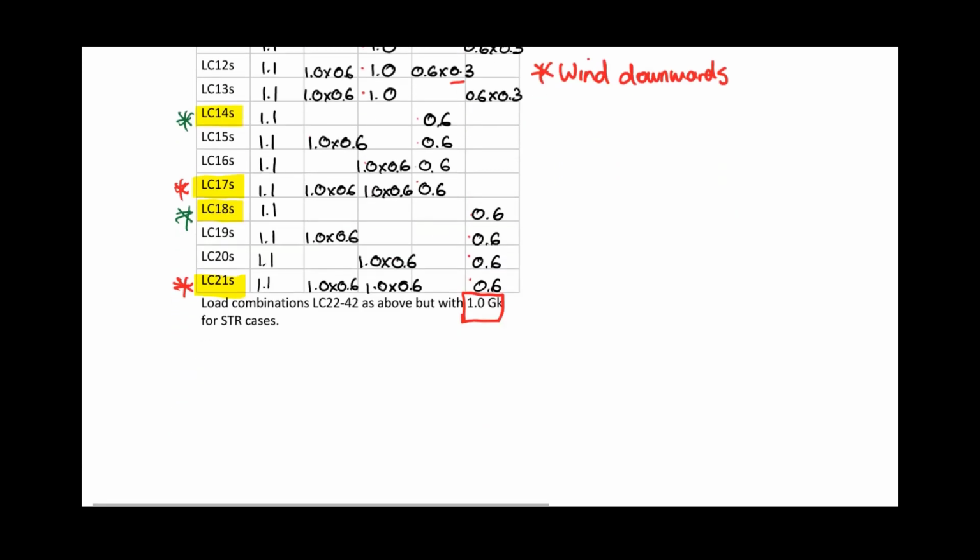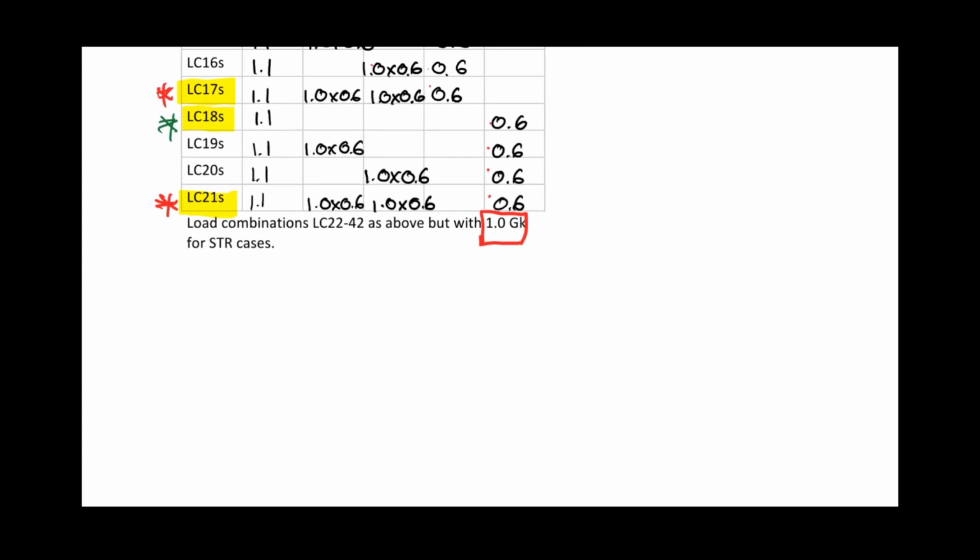And then just a final comment, finishing this one off, remember all of these were uncorrelated values, but you can have a time when loads are correlated. For instance, you've got a machine and you've got a lateral load and a vertical load, and the machine causes the same two at the same time. And then in that case, you'd have your 1.2 GK.